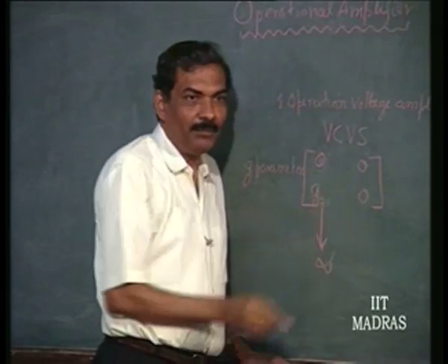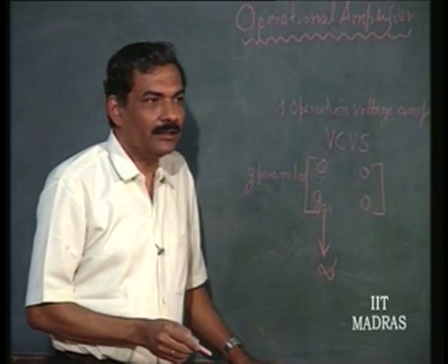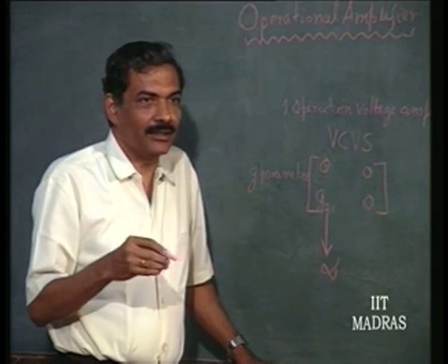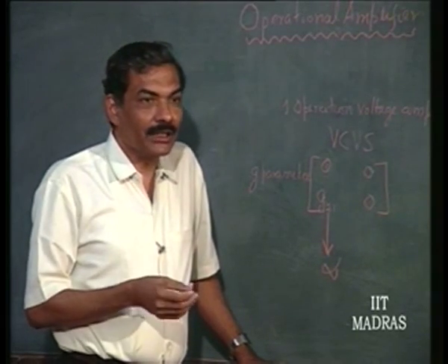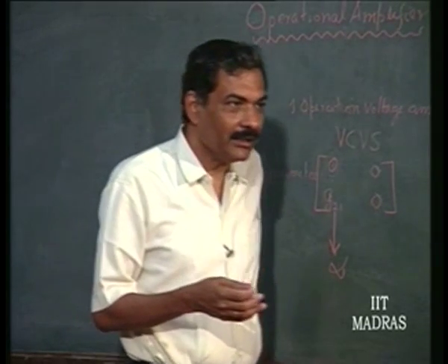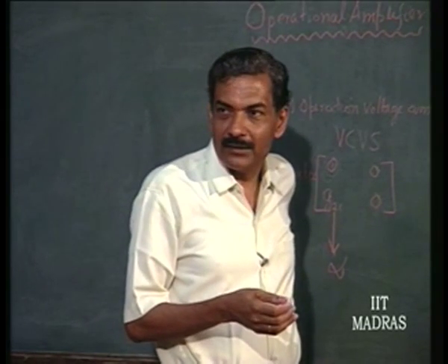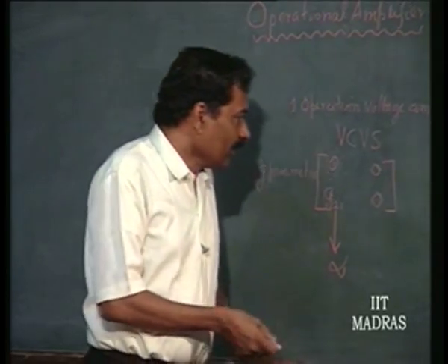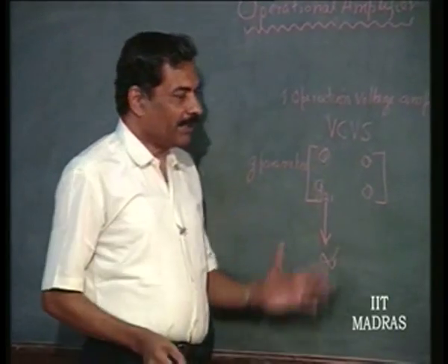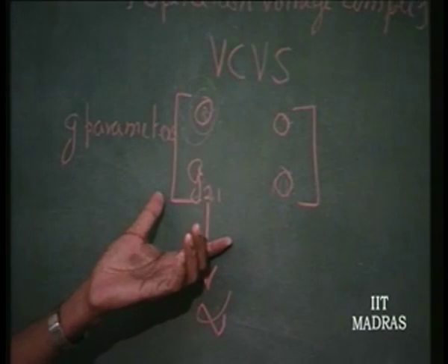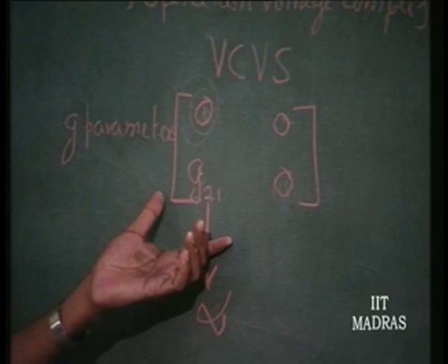As far as output impedance decrease is concerned, again we have seen that the output stage is going to be chosen such that it is a low output impedance stage. Automatically the choice is common collector output stage. So, the entire thing can be designed by simply noticing what the ideal device parameters should be.